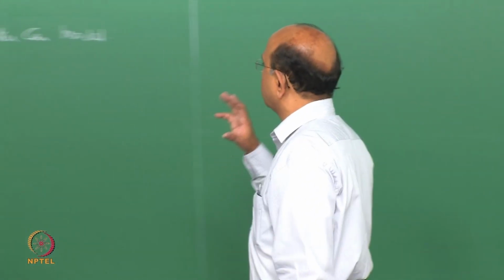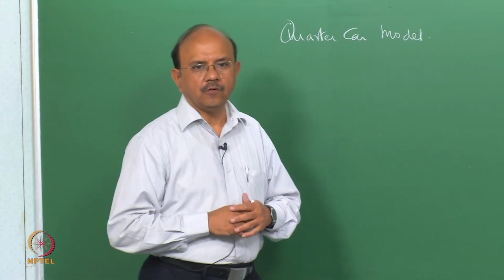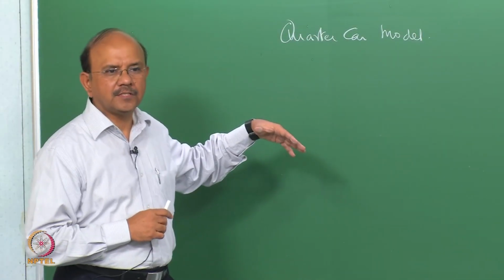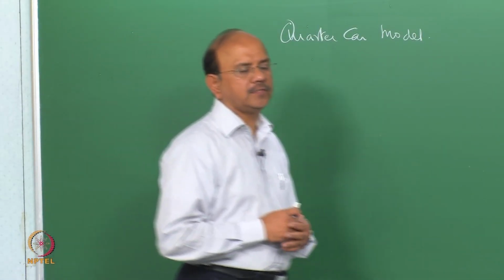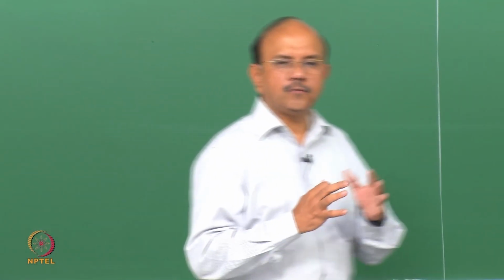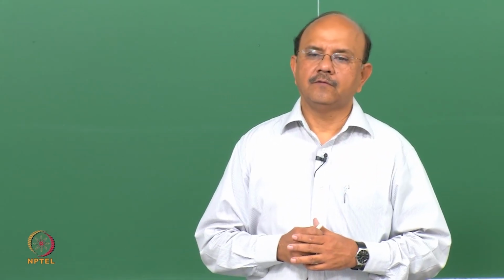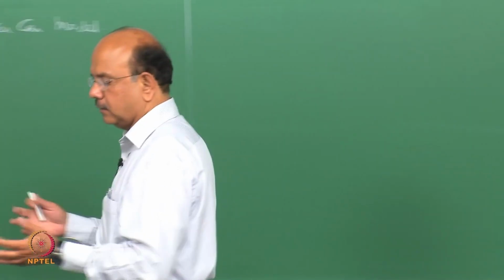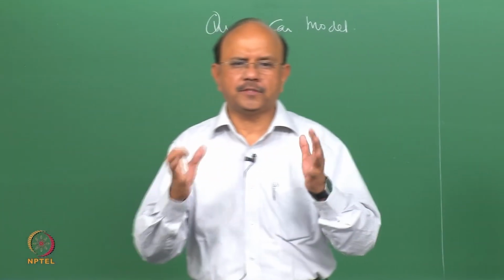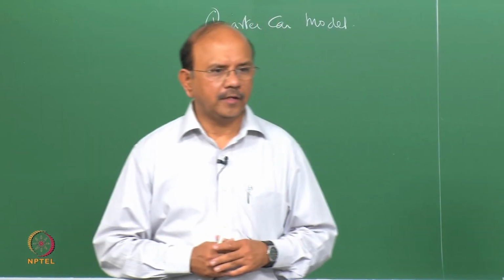So with unsprung and sprung mass, we were able to get certain equations which included the two natural frequencies. Remember that we can look at this from a very traditional perspective from vibrational controls. We can also write down the characteristic equation. We can do all those things. In fact, we can express this whole thing in state space. Maybe if there's time, we'll do it in one of the later classes.